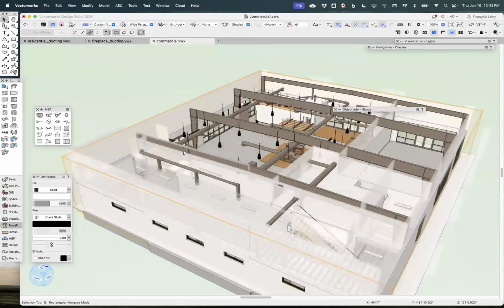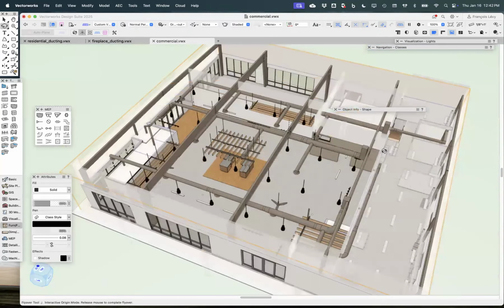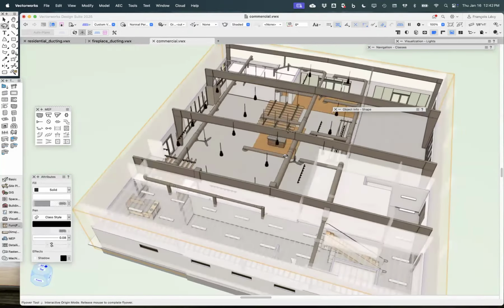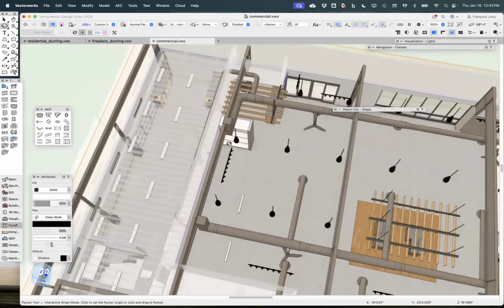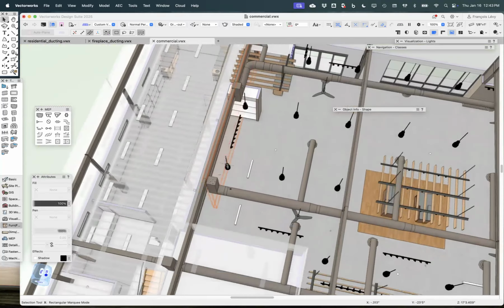And really, generating that wasn't that difficult. It was pretty quick to just trace over the MEP drawings. So we ended up having 3 RTUs here, which I didn't bother modeling because this was essentially an interior space. So here's one vertical supply duct from an RTU. You can see that I'm colliding with the steel beam. So that's probably not great. I'm pretty sure we ended up moving that over slightly. Here's another vertical from an RTU, and then here's the third RTU there.